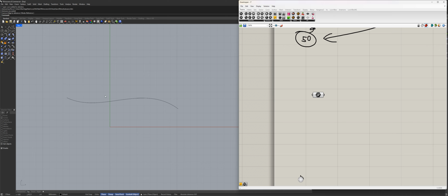No, you're going to see this curve in the Grasshopper is the original curve. This one is the streamed curve, and when I deselect, it hides itself, right? Now, if I click on the original curve and hide it temporarily, to do so I will type hide and hit enter. You're going to see that underneath there's actually another curve, which is a red one. What is this curve? Well, this is this one, just not active.